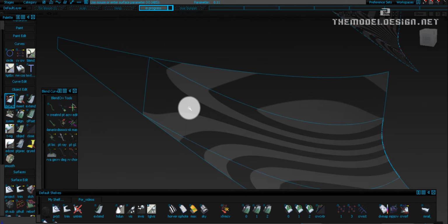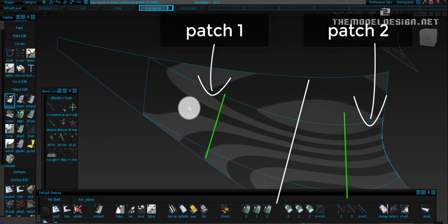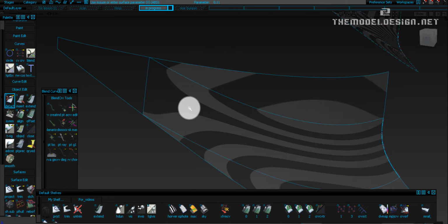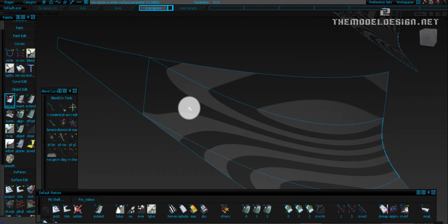A quick recap. The fillet surface was detached and each of the two patches received one span. By doing this, we ensured that we have achieved the G0 continuity by having sufficient number of CVs, and also we don't separate the surfaces into too many small patches. It's easier to work having two patches with one extra span each, rather than having 4 separate surfaces.